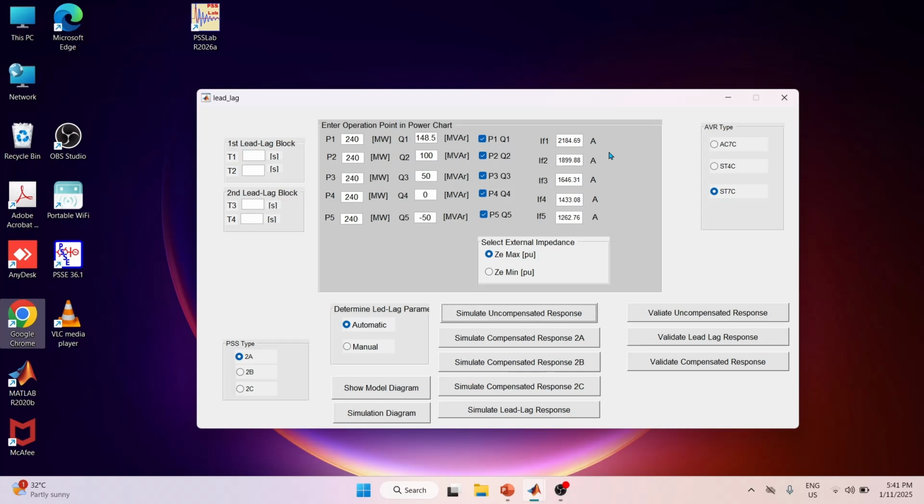This also indirectly verifies the values of synchronous reactances, stator leakage reactance, stator resistance, and the open circuit characteristic, because the field current is derived from the reconstruction of the generator phasor diagram at a certain operating point. Furthermore, this will give confidence that the parameters of the sixth order generator model after linearization are okay.